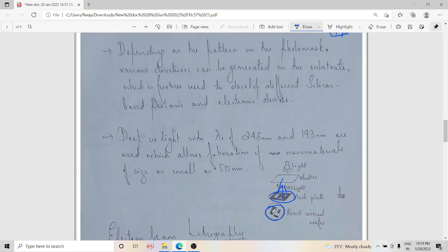In a positive photoresist, the exposed regions get washed off. Whereas in a negative photoresist, when you wash it with suitable solvents, the unexposed region gets washed off. Now, this depends on the type of image that you need to develop on the surface of the film. After this process, we follow techniques like etching or lift off so that you get the desired images on the surface of the silicon wafer. So this is the